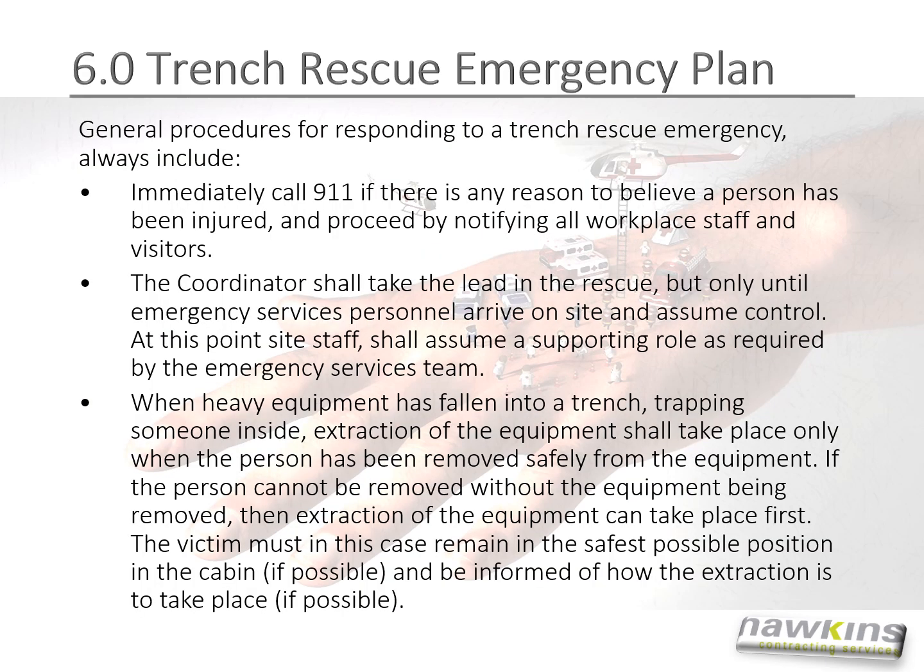General procedures for responding to a trench rescue emergency always include immediately calling 911 if there is any reason to believe a person has been injured, and proceed by notifying all workplace staff and visitors. The coordinator shall take the lead in the rescue, but only until emergency services personnel arrive on site and assume control. At this point, site staff shall assume a supporting role as required by the emergency services team.